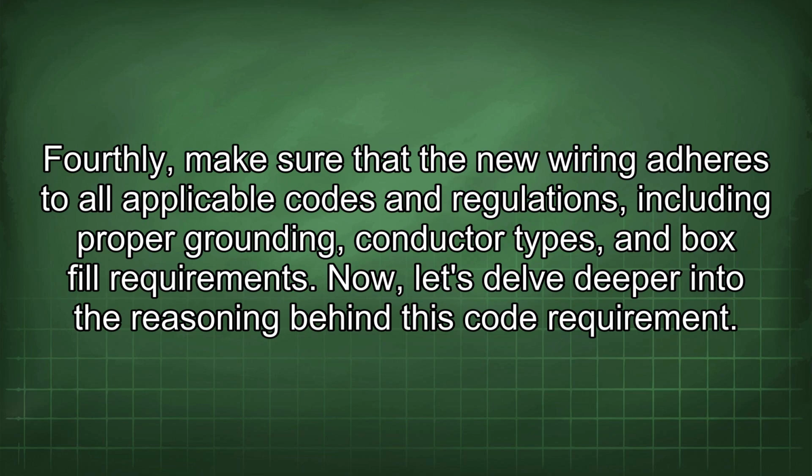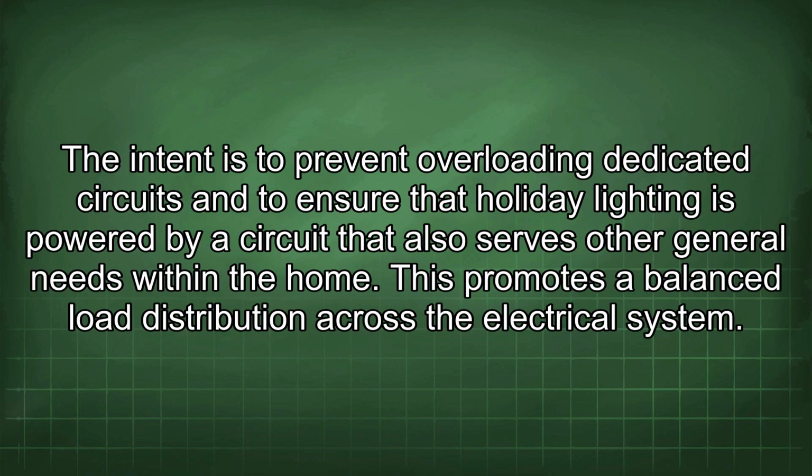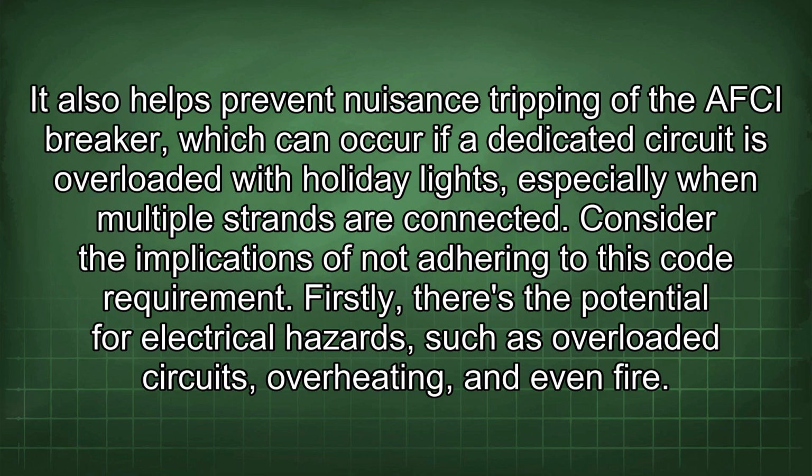Now let's delve deeper into the reasoning behind this code requirement. The intent is to prevent overloading dedicated circuits and to ensure that holiday lighting is powered by a circuit that also serves other general needs within the home. This promotes a balanced load distribution across the electrical system. It also helps prevent nuisance tripping of the AFCI breaker, which can occur if a dedicated circuit is overloaded with holiday lights, especially when multiple strands are connected.